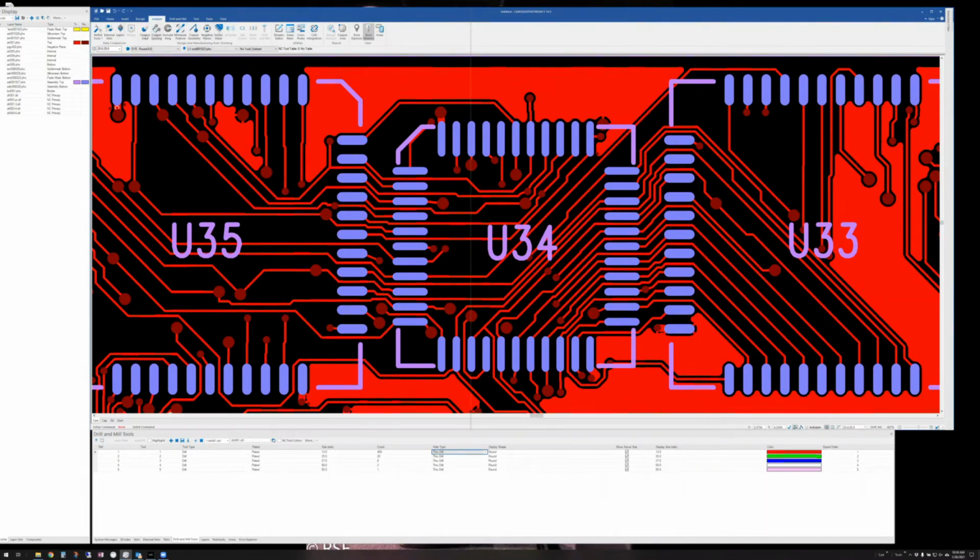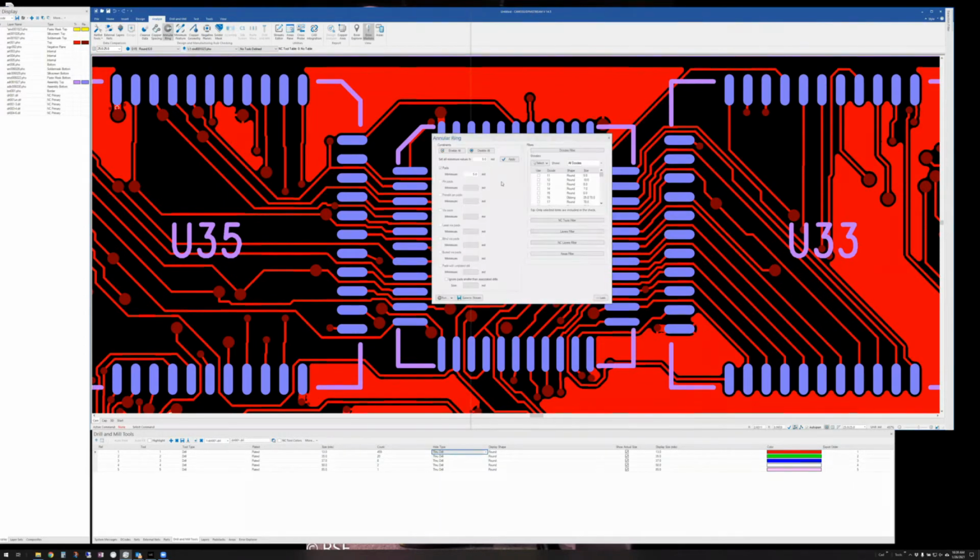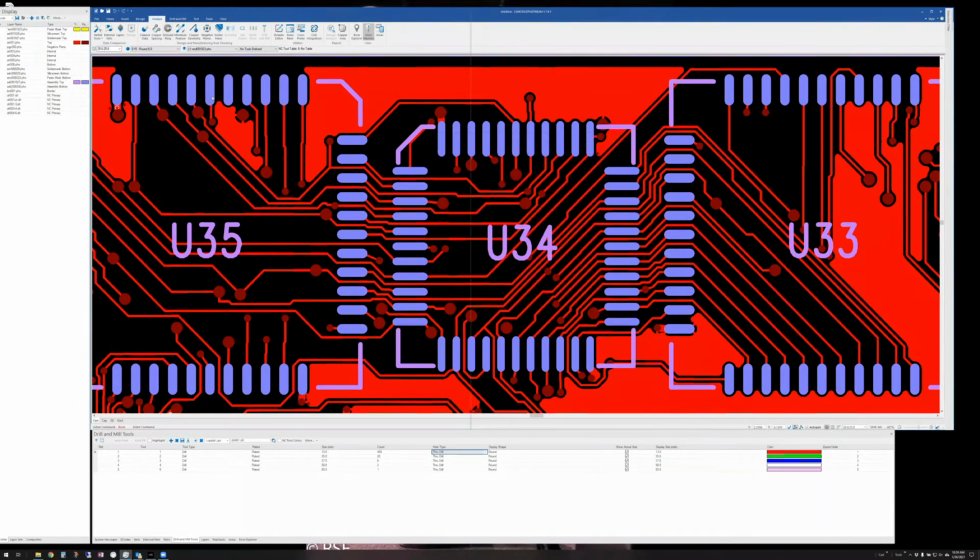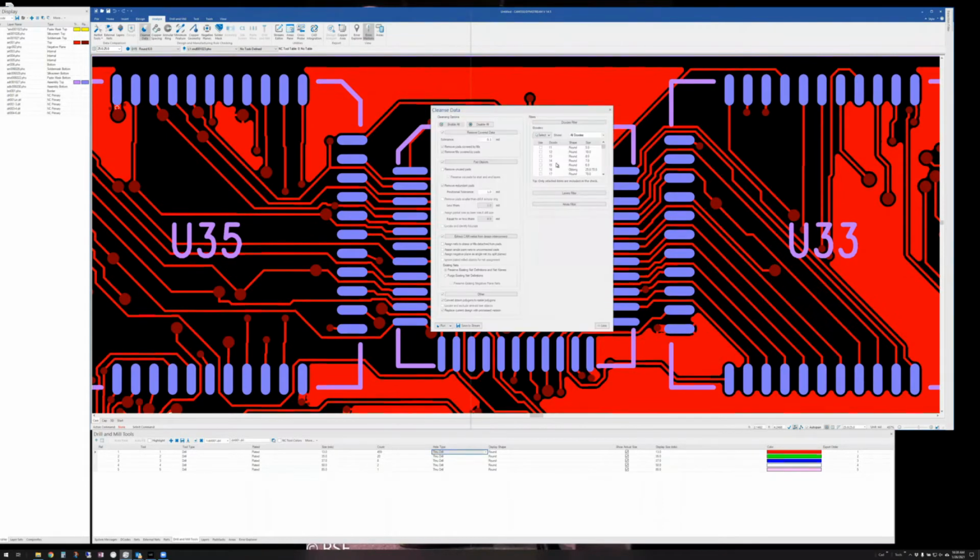And then we get into the other analysis capabilities, which are your DRC and your manufacturing rules. And again, because it is the 160, the only thing enabled in here is, in this case, 1 annular ring check. Okay, and I can set that value and then run annular ring. If I had the higher end, I could have a different value for via pads, which would be the mechanicals. And if I've set up any laser vias, they could have their own, or I could have different values for buried and blind. It's up to me how I set that up, but again, I'm pointing out the differences between the two.